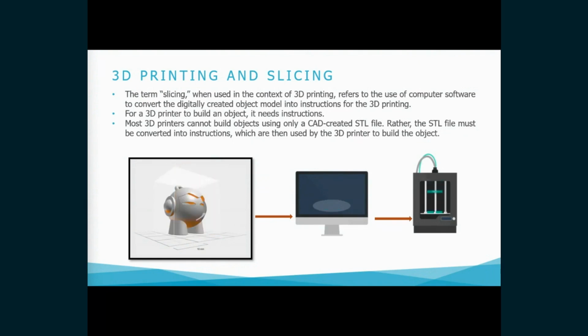3D slicing is the process of breaking down a design into several layers. It simply involves cutting a design in layers. Slicing software takes scans of each layer of the model and will tell the printer how to move in order to recreate the layer. Slicers also tell the 3D printer where to fill a model.